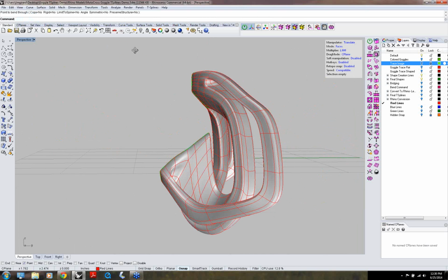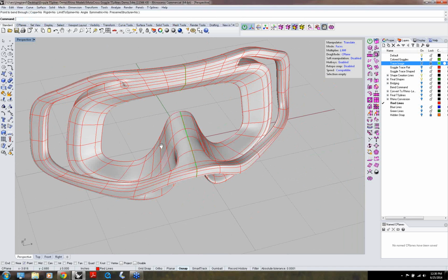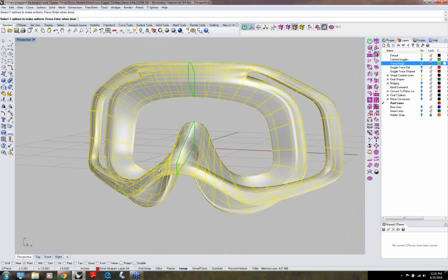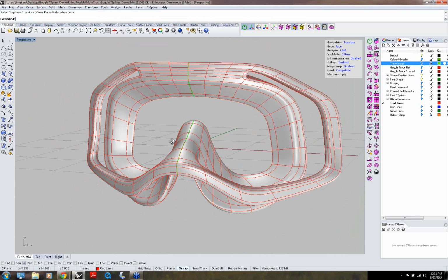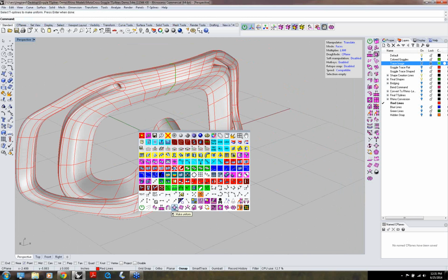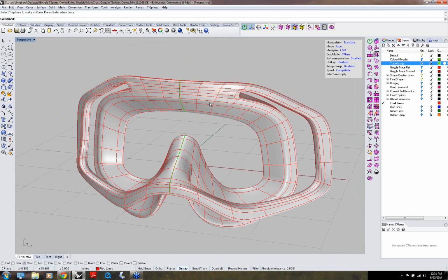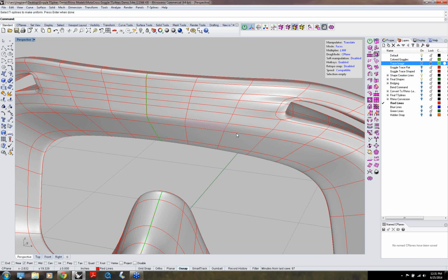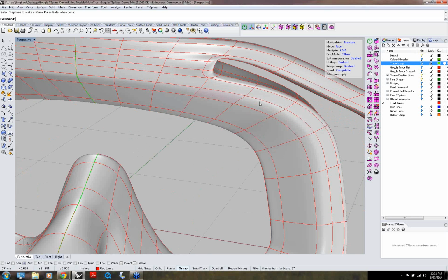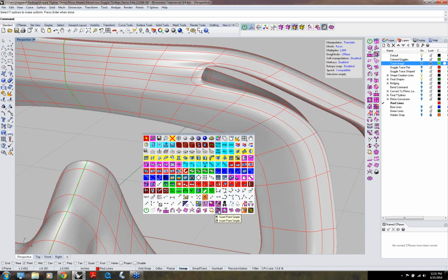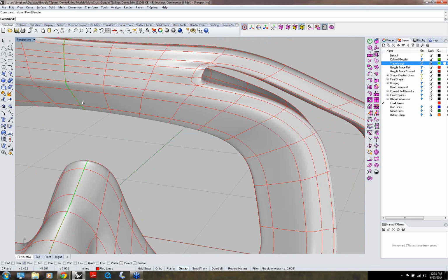And now you have a really nice surfaces going on. Again, I always do the command for making uniform. Now you could have a little fun. You can come up here and say, you know, I want this to be like a variable radius. I want this edge to be really tight up here, but when I get down here, I want it to wash out. Well, there's a command called insert point simple, and you just come over and pick where you want it.